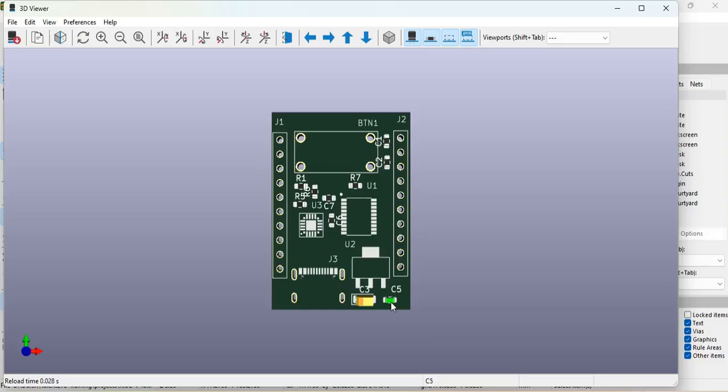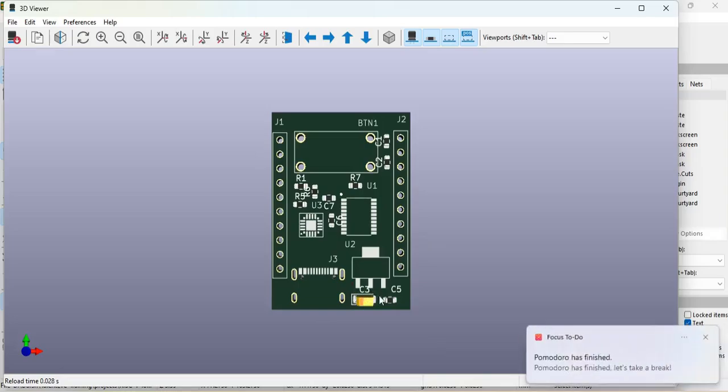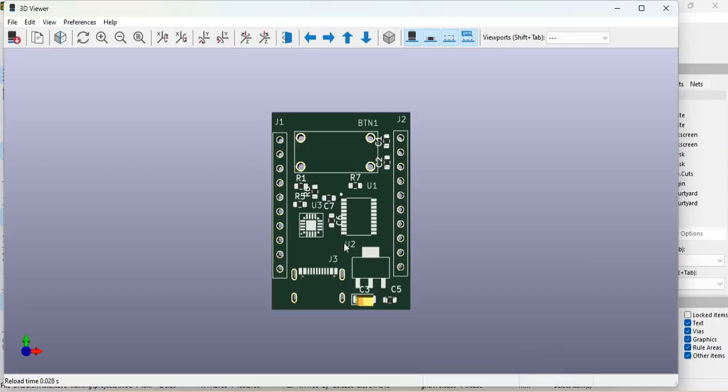Now in case you feel you cannot, let us assume you cannot move C3 either here or there, and you want the component C5 to be moved towards the right side to accommodate C3. You can also take a call on completely eliminating C3 from the PCB.